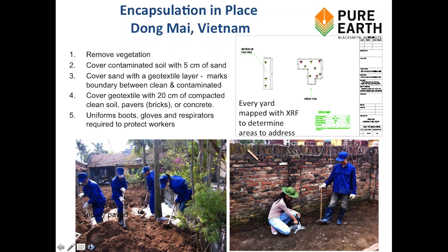The depth of soil is a touchy issue. The greater the depth, the more you have to worry about drainage, about how this compares to surface levels in the surrounding houses, and how you're going to handle that increased elevation of the property.